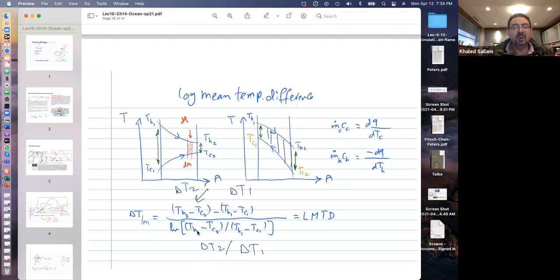as this formula. So what does this formula say? It says that here's your delta T at the exit, here's your delta T at the inlet. Your actual delta T should be delta T2 minus delta T1, over ln of delta T2 divided by delta T1. So ln of the division, and on top you have delta T2 minus delta T1. And amazingly, or luckily, it doesn't really matter which is delta T2 and which is delta T1. You would think delta T1 has to be the inlet and delta T2 the outlet. Sure, but it doesn't really matter.